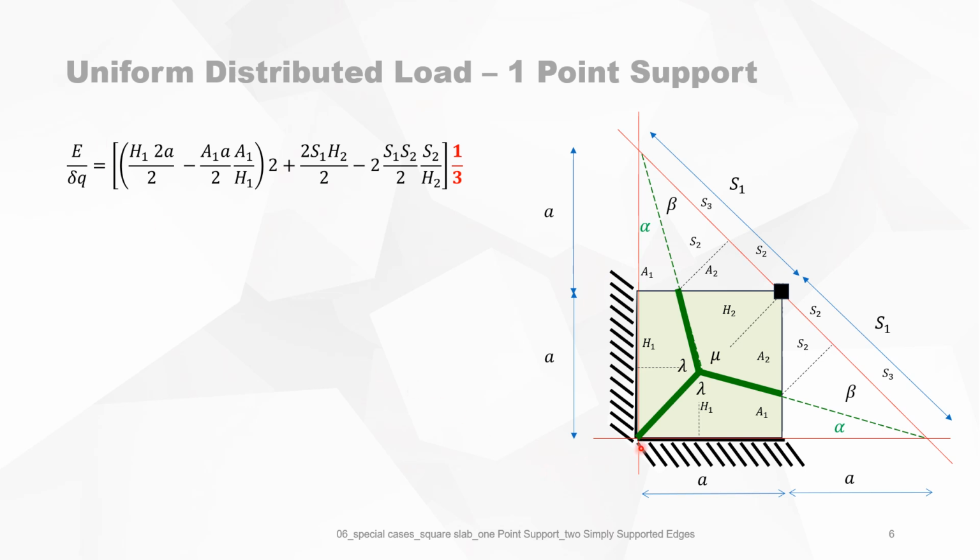When we look at the total picture, it can be very difficult to calculate the mean deflection of a piece like this, or a portion of the concrete like that, when this is delta and this is a portion of delta. But we can do it in an easier way by seeing that the whole picture is in fact a summation of triangles. You got this triangle, and this one, and the big triangle there. So everything is a summation of triangles. That's why we take delta over 3 as the mean deflection.